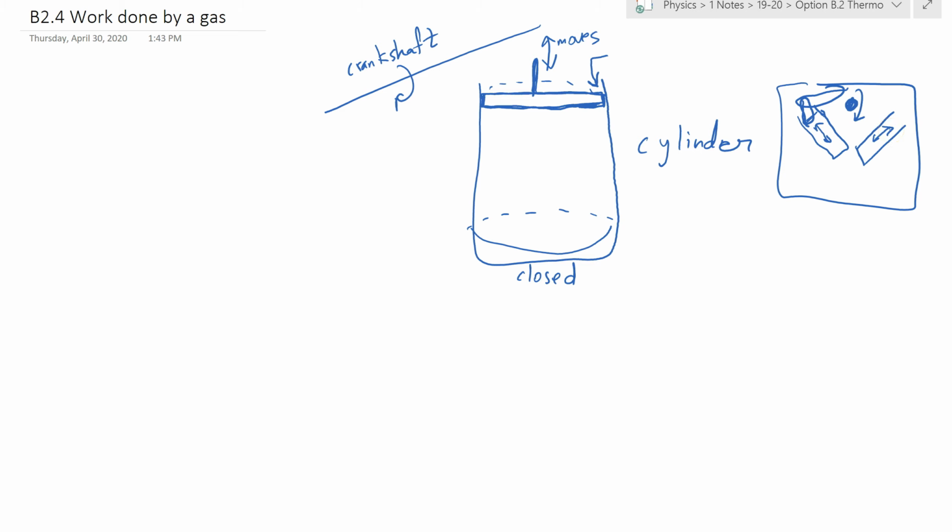And if you have 4 or 6 or 8, or in crazy cars, 12 pistons, they have to be timed. Ideally, you want one of those pistons always to be applying a torque to the crankshaft so that it always is experiencing a torque to cause it to keep rotating. And if you time them cleverly, then each of their power strokes, which is when they're pushing on the crankshaft, happens at a different time, and they're sequential.